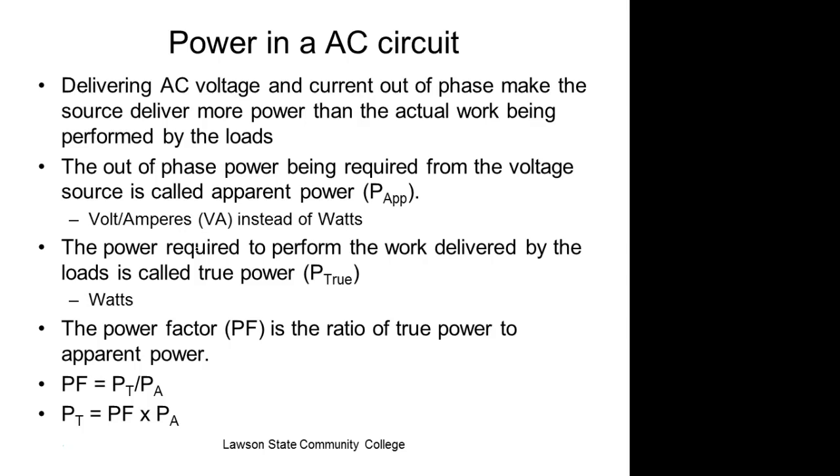By the way, the closer you run your motor to its rated load, the less it shifts the phase, because it's inducing a voltage back into the motor. We'll look at that later on. So if you're going to buy a 30 horsepower motor running a 5 horsepower load, then you're going to be paying more than what you think you are. So when you engineer these things, you need to buy a motor as close to the horsepower that you need to run, because the phase shifts they create are a lot less.